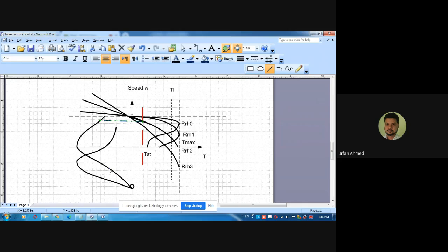For braking, you always need flux. You always need a flux. And as soon as you disconnect the supply, your flux disappears. Okay. So my question once again is, how do you obtain dynamic braking in an induction motor? Yes, anyone?